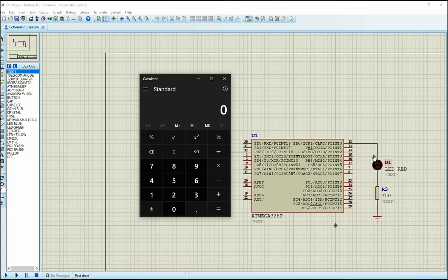So the way you do that is you subtract the voltage drop of the LED. This is a red LED, which means, according to the data sheet of most of these LEDs, the approximate voltage drop is around 2 volts or 1.8. So assuming that I've got 5 volts there, I do 5 minus 1.8, which is 3.2. Then I divide it by the resistance, which is 150 ohm in this case. So I got 21 milliamps. So there will be 21 milliamps that will go down there.